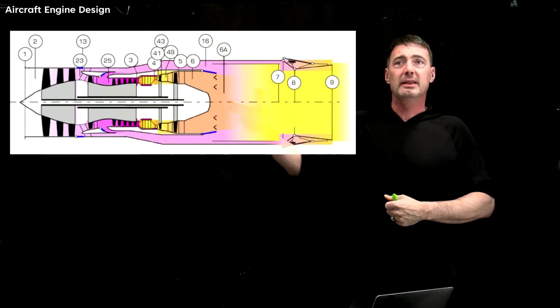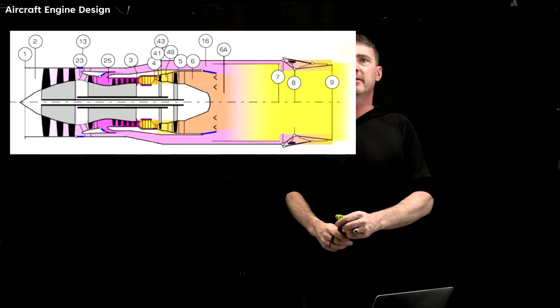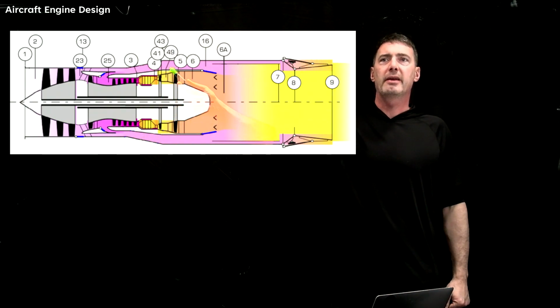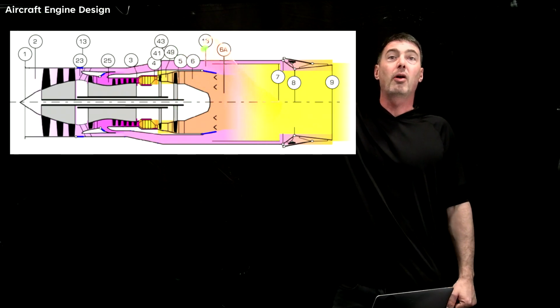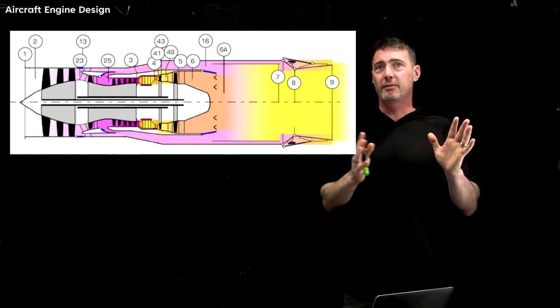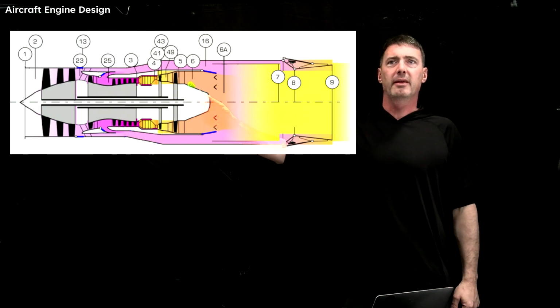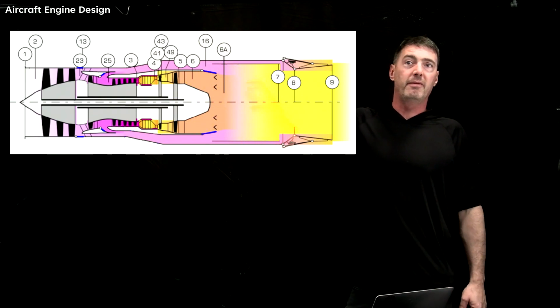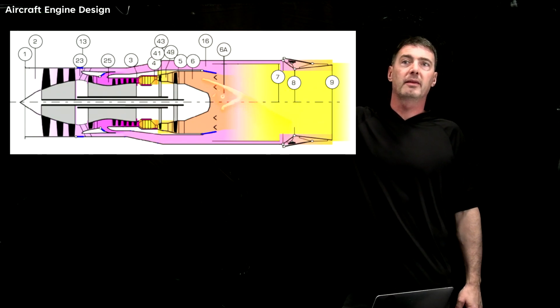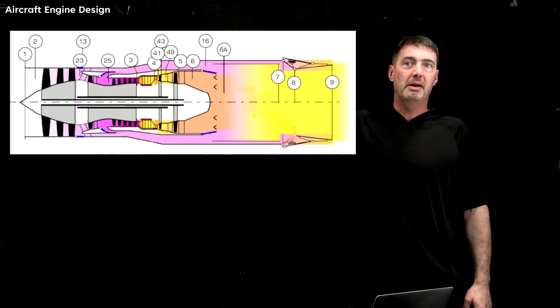Okay, 3 is the combustor inlet, so combustion is happening here. And then 4 is the combustor outlet. And now it's the turbines. 4.1 would be at the first turbine blade, 4.2, and so on all the way through all of your turbines. If you have a high pressure, low pressure split, you just keep counting. 5 is the turbine exit. Then 6 is sort of the fanning out here, an exit versus the duct, because you're now bringing the core down. And so you may talk about trying to match the speed here between what's coming out.